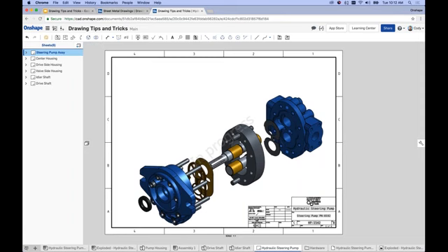Why do I need to see the view reference info in the sheet list? Isn't this a view property? Having it appear in the sheet list makes navigation using the sheet list cumbersome. I don't agree. In this case, you'd have to know whether it's the assembly you're referencing or a part within the assembly that you're referencing, and that is related to the entire sheet. Today, that's not a view-specific thing. So that's an important thing to understand. The reference for any sheet is at that sheet level, not individual view level, right?